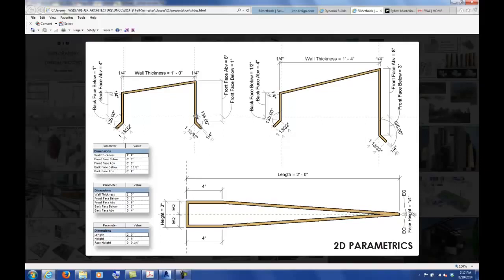example would be, in SketchUp, if you have a window that's 5 foot by 10 foot and it has a horizontal mullion and a vertical mullion, well, then you might have another window that's going to be 5 foot by 4 foot. What do you have to do? You actually have to do a save as of that component, and you have to remodel that or make the changes on that, and you have a whole other separate file that has to deal with that other new window.